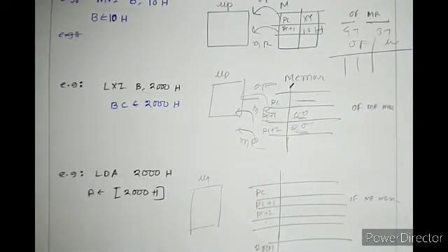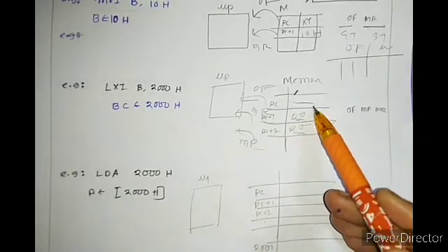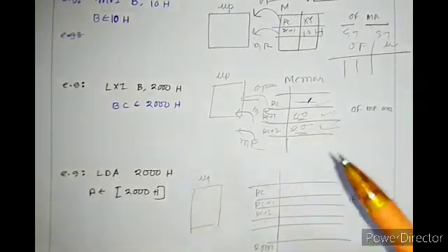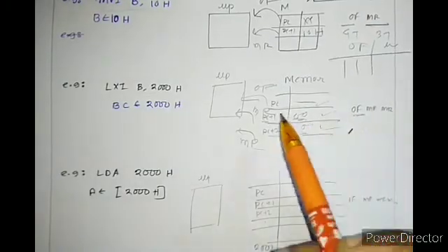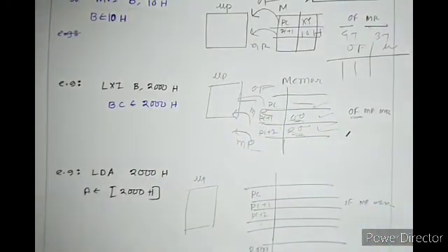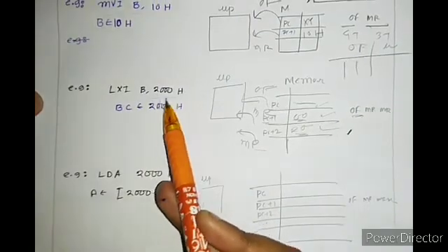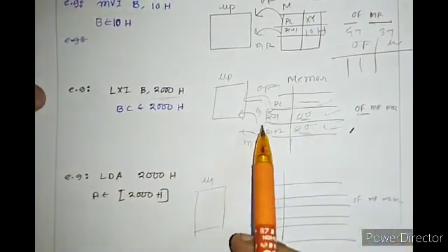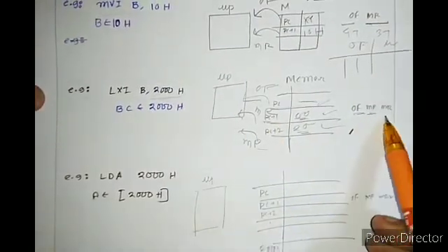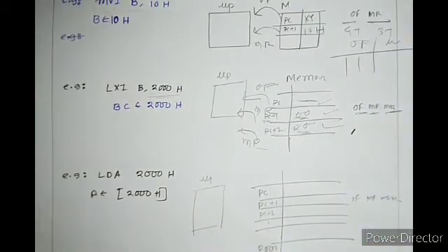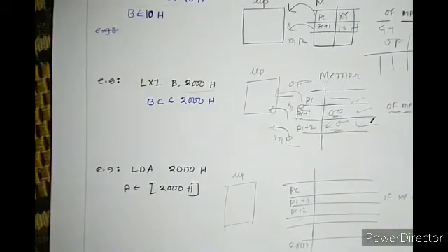Okay, so how many T states are required here? First, at 3 memory locations they will get stored. First opcode fetch, obviously, then get this data from 2 memory locations. So MR, then also MR. Okay. Next is LDA 2000, meaning load accumulator.